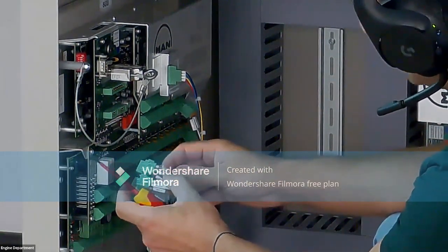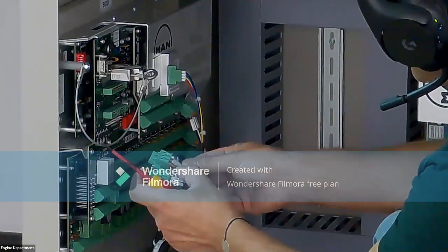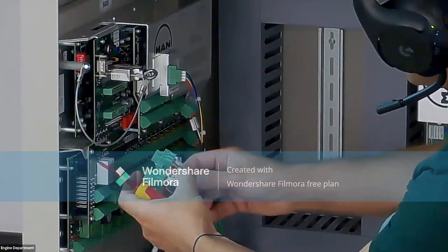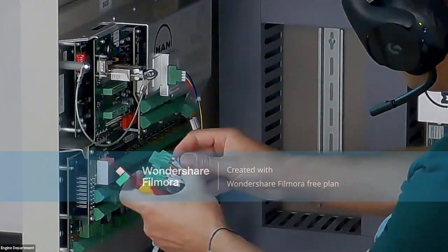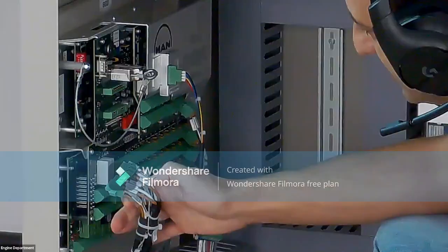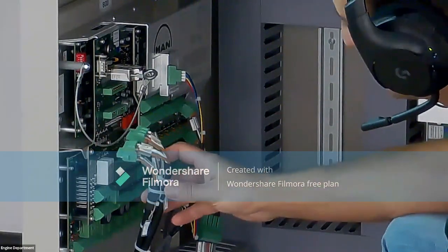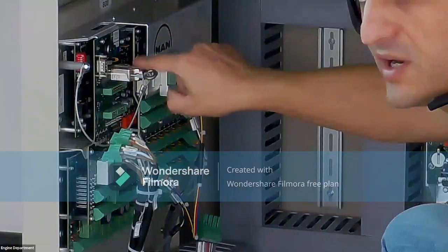As I told you, each plug is tagged with the number according to the connector it is required to connect to on the MPC. So each wire is tagged accordingly with the connector number available on the MPC. After you disconnect the network, disconnect the ID key.